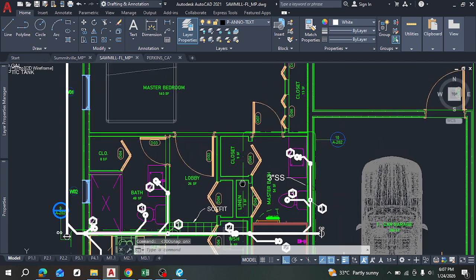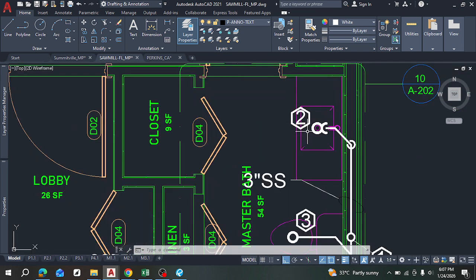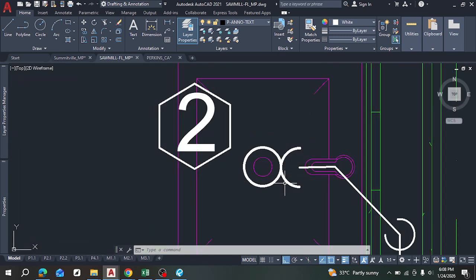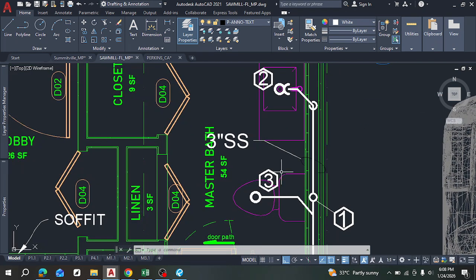Okay, so this is what it looks like after, right? So now this is just showing where the drainage line collects, where it meets the fixture, and this is to indicate a strainer, and that strainer is usually used in fixtures that should not allow solid waste to pass through, right? So that's what this basically means. It has something like a gauze, right? But in WCs let solid waste pass through it.